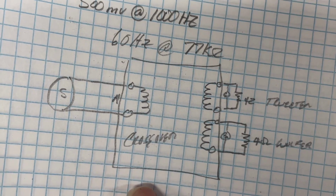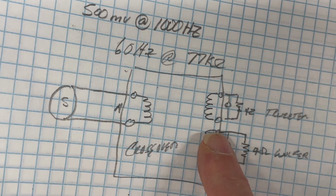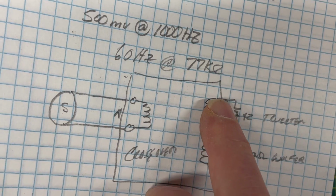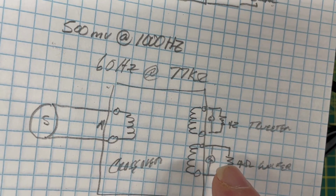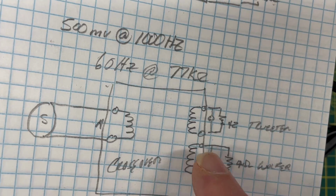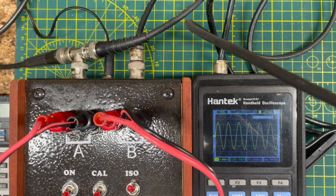So here's our setup for the crossover. We have the signal generator hooked up to the input of the crossover. We're going to be looking at the woofer or the bass speaker output first, and then we're going to look at the tweeter output. So right now both of these outputs have 4 ohm resistors across their outputs, and the scope is tied to B. And we've set the output voltage up here to 500 millivolts.